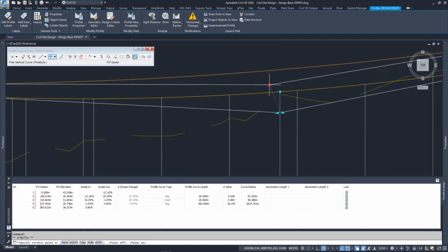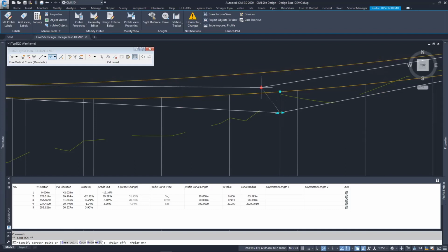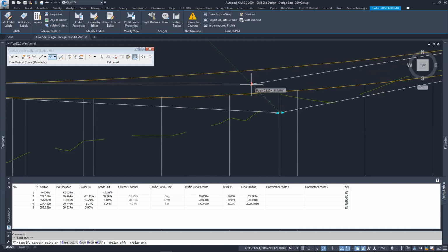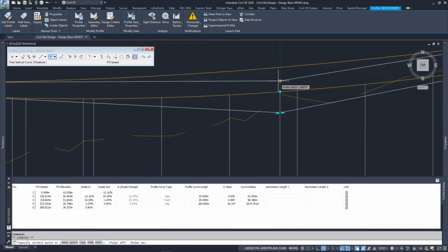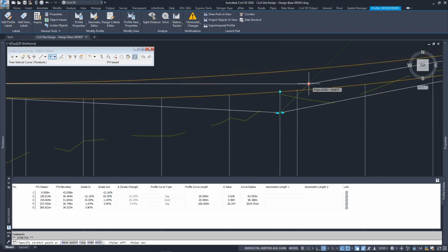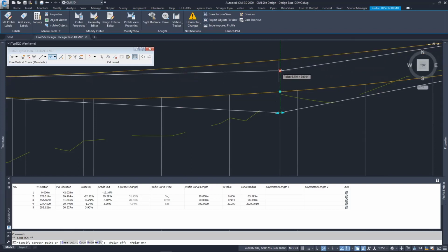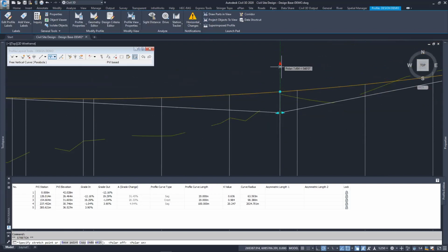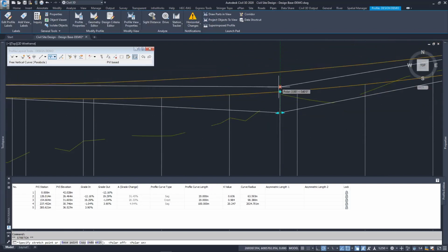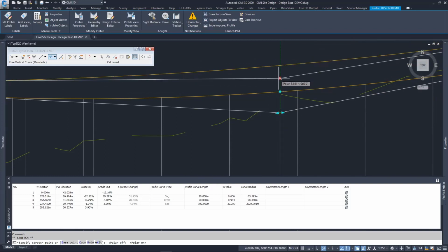But with this one, I've got a semi-snap, for lack of a better word, where I can choose. I've got it set currently to 45 degrees. So if I want a 45-degree adjustment, I can use that. But I've also got the vertical adjustment, and I've got that snap as well. So I can control my vertical movement.